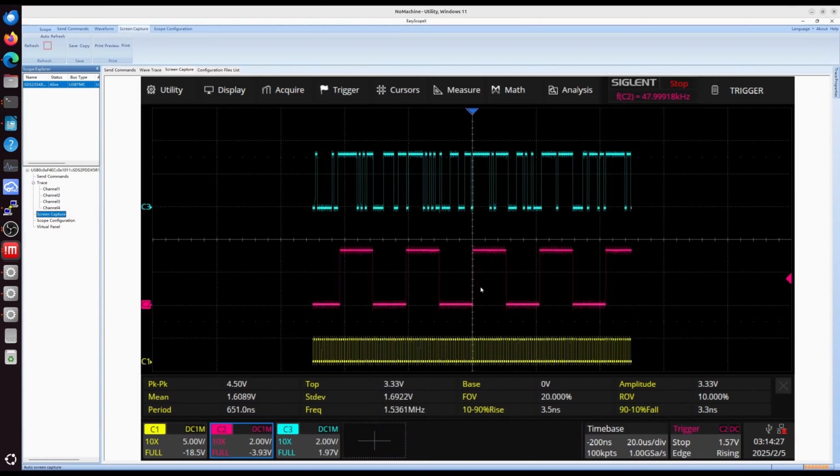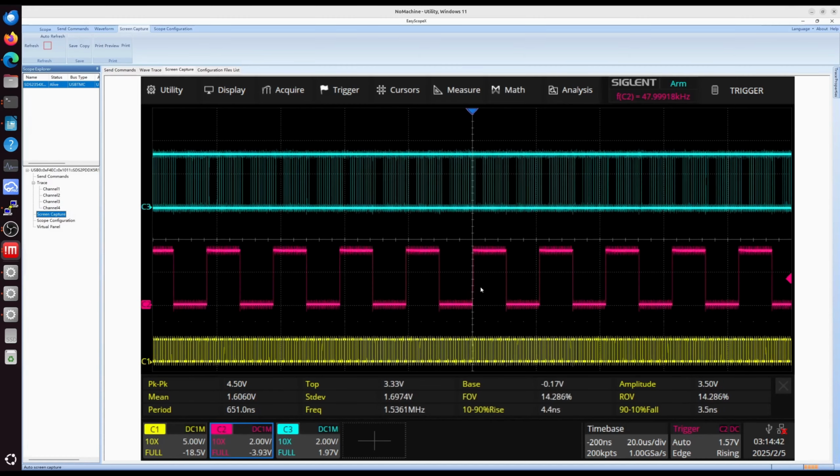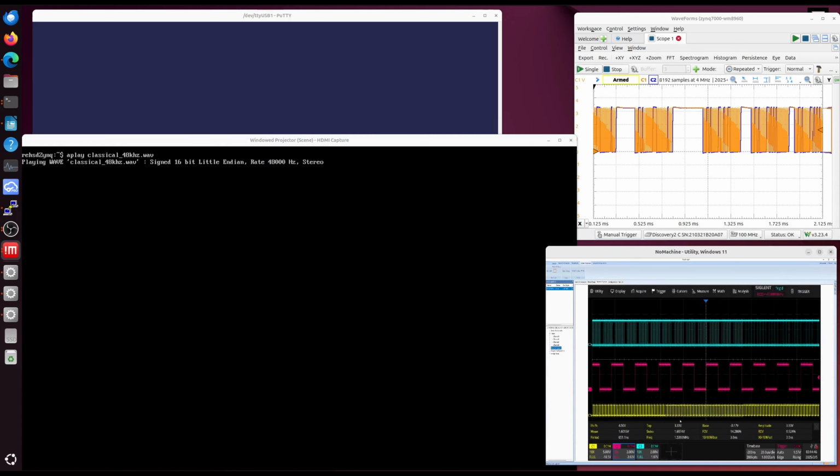The frequencies are looking good, and if I make a good connection from my scope to the board, you won't see those little spikes above and below. But right now you're seeing that, which isn't a big deal. I'm going to go back to auto and just let this run. I'm seeing good activity here, and here. That would be those five signals that I have connected to the board.